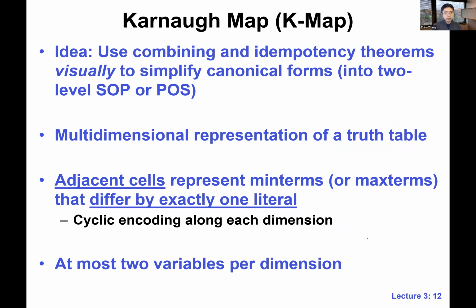And the important thing about Karnaugh map, make sure that you focus on this: to understand a Karnaugh map, the very important thing is to understand the intuition behind adjacency. So what exactly is an adjacency? What does adjacency mean in a Karnaugh map? We already saw some of this when we looked at the C out column for this binary addition. When two terms differ by just one literal, that's where we have the opportunity to combine. So this is what we mean by adjacent.